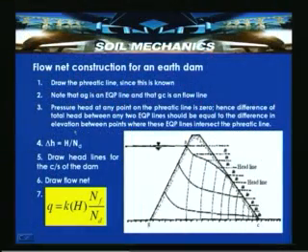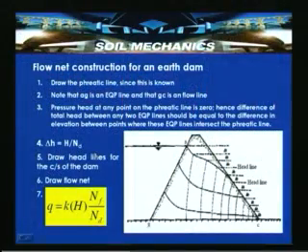So, as the pressure head at these points is 0 along the equipotential line, the difference in elevation between points where the equipotential lines intersect the phreatic line can be taken as potential drops. So, delta H is equal to H by ND, where ND is the number of potential drops.